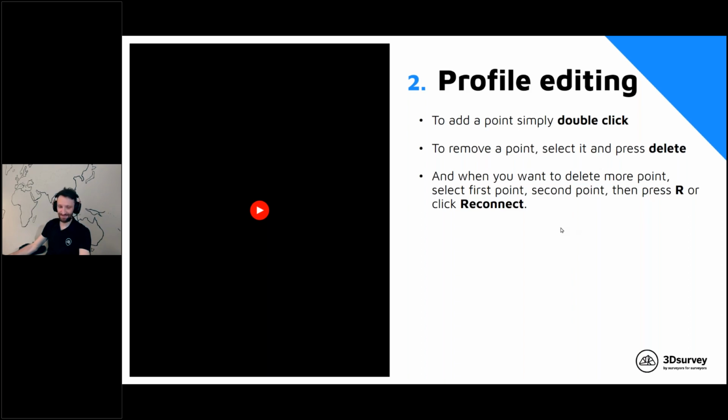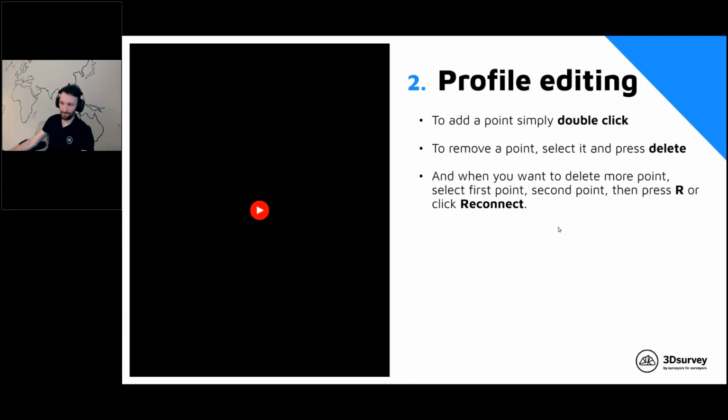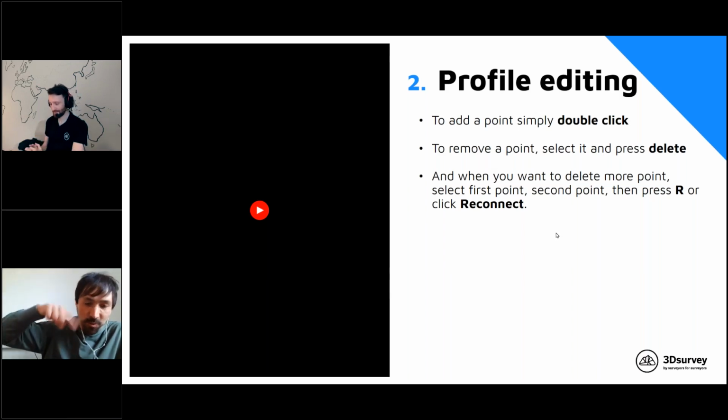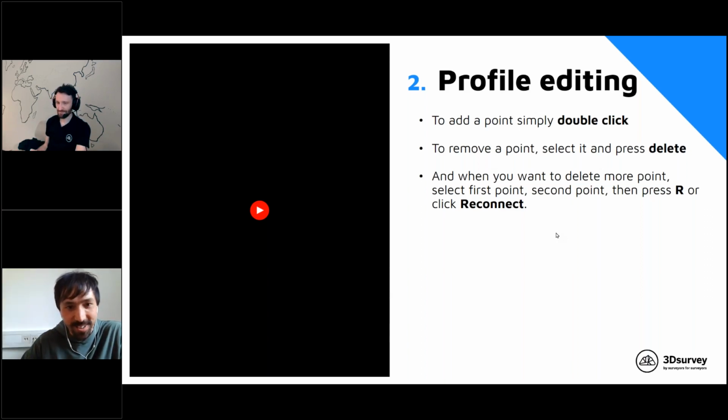So this one is super nice. Now you have a classified point cloud and the profile was immediately nicely connected. But from the user feedback, sometimes they forgot to do the classification before the profiles, and then they get, I don't know, 500 vertical lines with a lot of these annotation points. They are upset, oh, how to do it. And actually, I know a few of our customers that were doing this for 2 years, deleting point by point. This feature is inside for more than 5 years, and yes, great that you mentioned it.